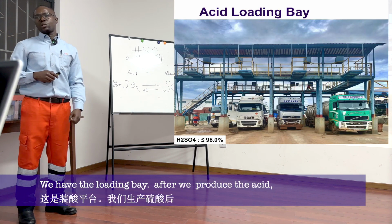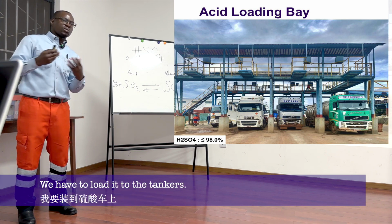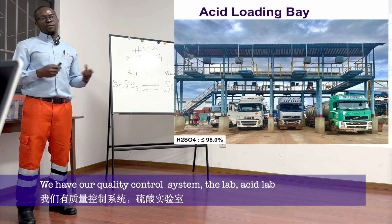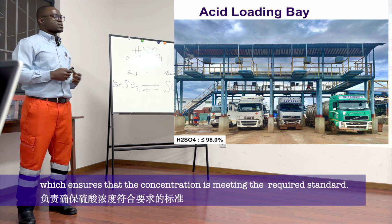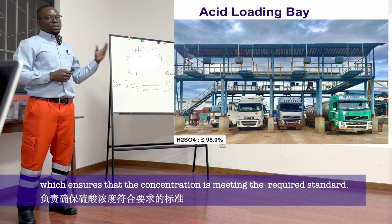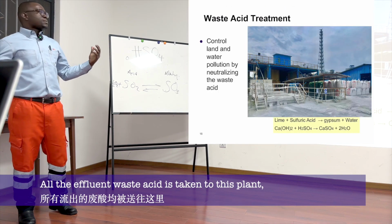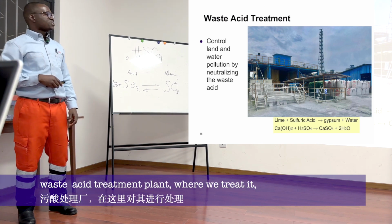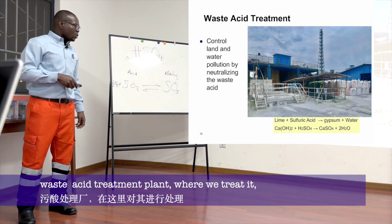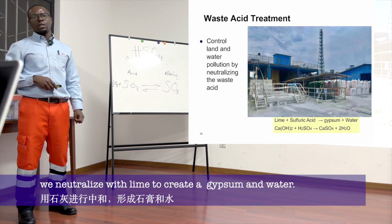We have the loading bay. After we produce the acid, we have to load it to the tankers. We have our quality control system, the acid lab, which ensures that the concentration is meeting the required standard. All the effluent, the waste acid, is taken to the waste acid treatment plant, where we treat it, we neutralize with lime to create gypsum and water.